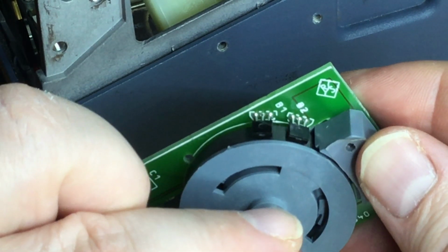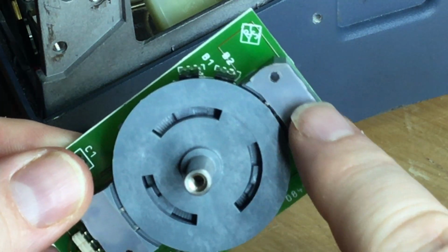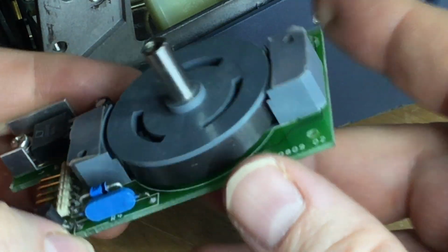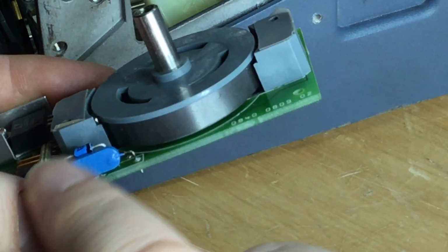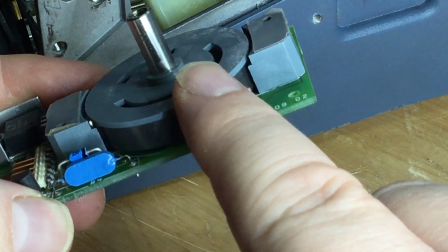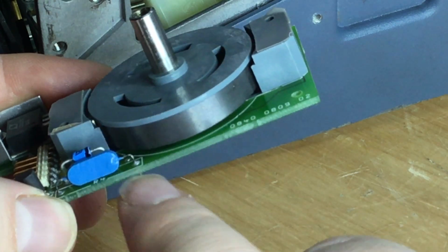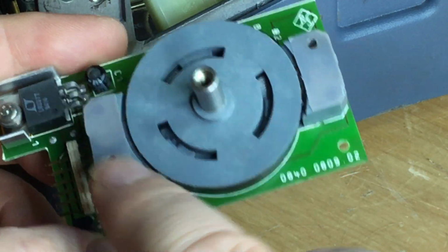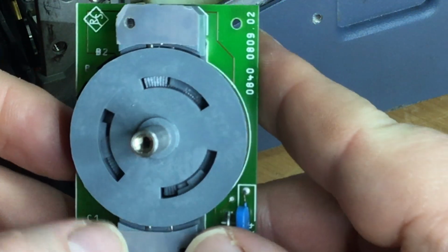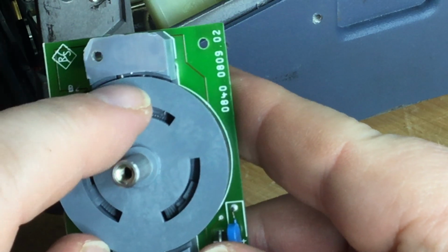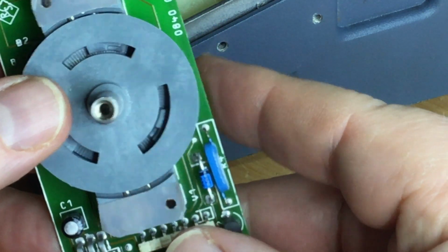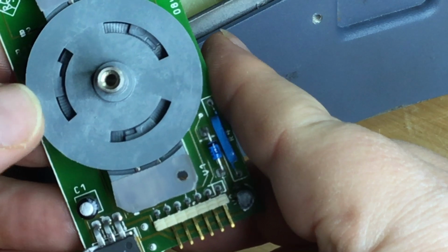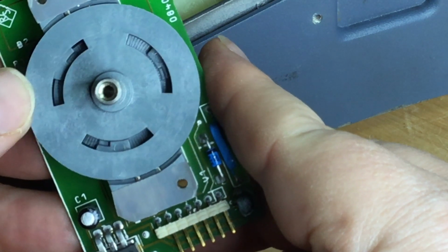But I have noticed, looks like these two, that one and this one down here, they're magnets that repel the indents on this disc, because obviously this disc has got north south poles all the way around it, so there's two permanent magnets with field poles that are very, very sharp, as you can see just there, those little metal things, and two there that effectively give it its indentation. You see, it's going round, it's repelling it.